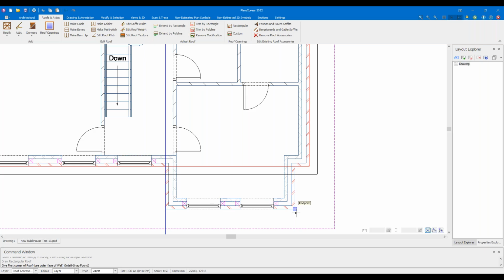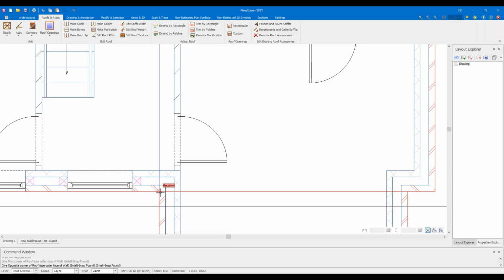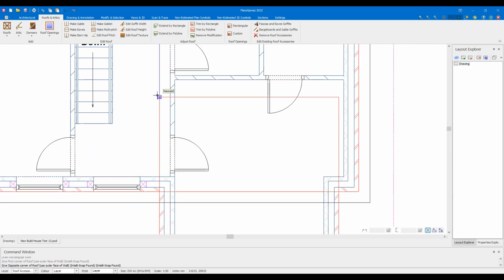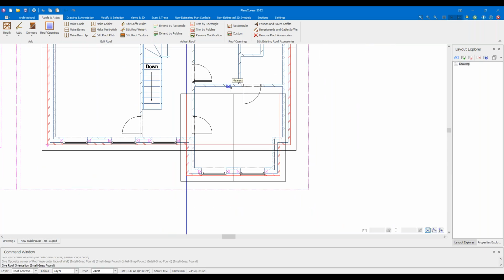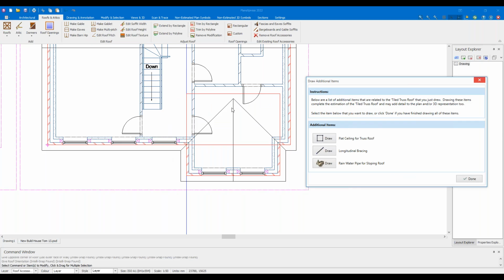I'm going to click, bring my box in here, and I'm actually going to snap it to my construction line here. Now I could hover over a corner here, like we did with the wall practice, and bring it up in line, but the construction line just makes life a lot easier. Once I've done this, and I know I've got enough overlap to form valleys, I can left click, confirm the direction of my ridge, so front to back. If I go to the sides, it gives me a mono pitch. I don't want that. So front to back, left click, place. And now I have my valleys.